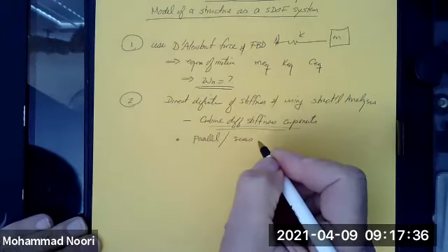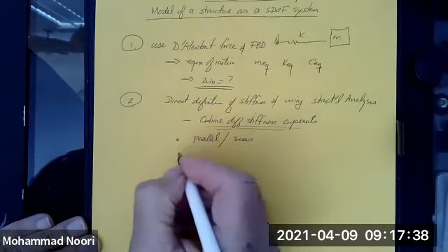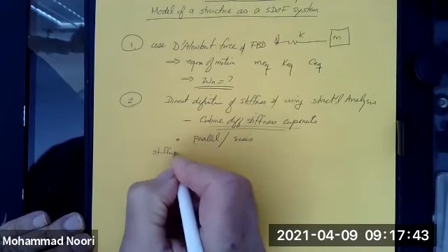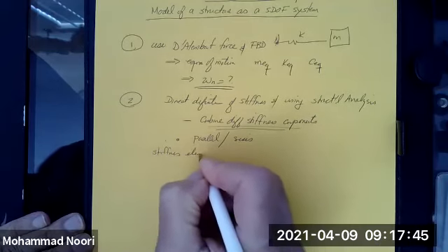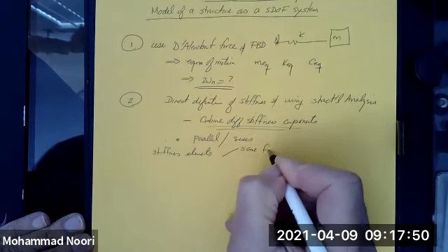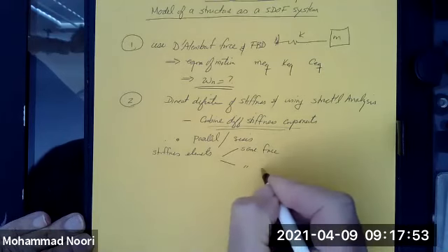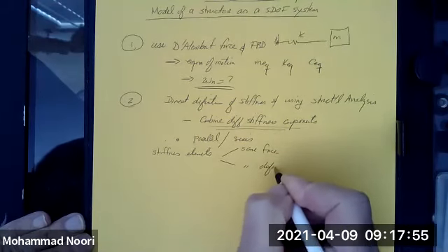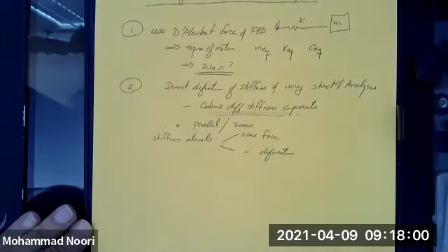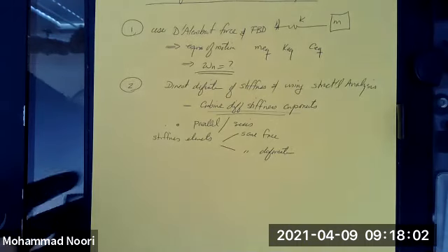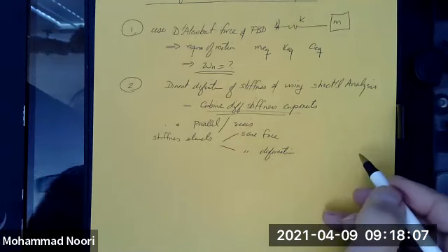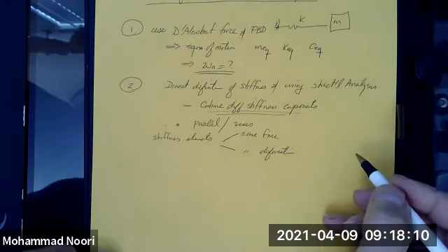I emphasize that a better description is that the stiffness elements experience the same force or the same deformation. Geometrically, you may have springs that seem to be in series, but they're actually experiencing the same deformation. So by this terminology, they're actually in parallel.